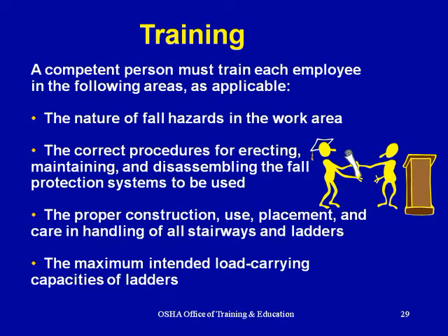Training. A competent person must train each employee in the following areas as applicable. The nature of fall hazards in the work area. The correct procedure for erecting, maintaining, and disassembling the fall protection system to be used. The proper construction, use, placement, and care in handling of all stairways and ladders. The maximum intended load carrying capacities of ladders.